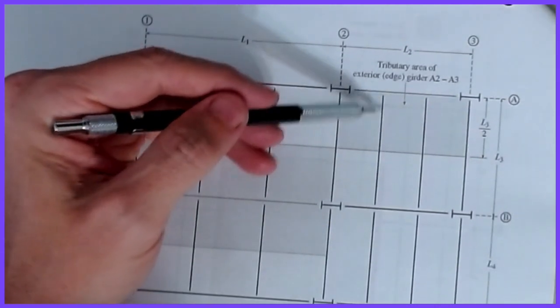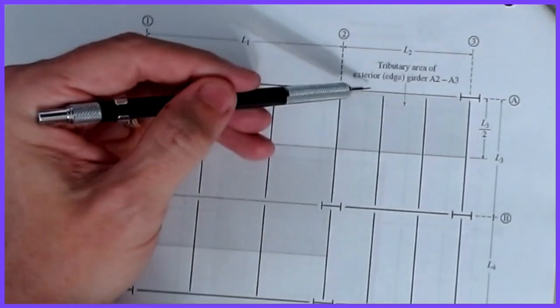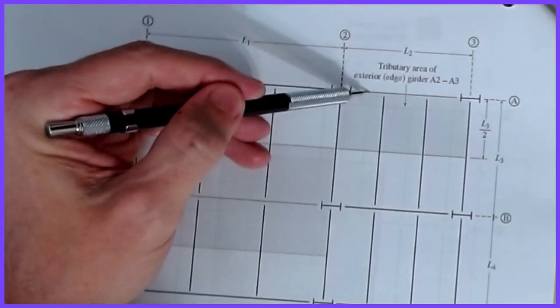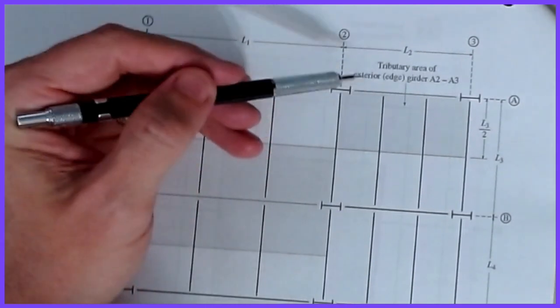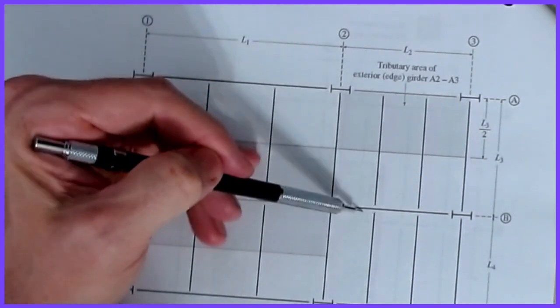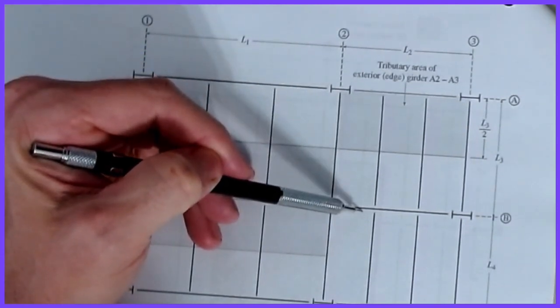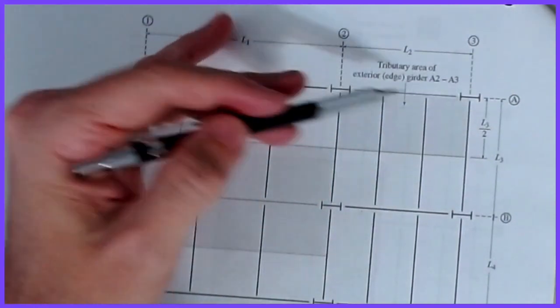So just like the beams, where I had my beam and I took half to his neighbor and half to his neighbor this way, the girders work the same way. If I just want to get a sense of the magnitude of the load, it's not exact, but it is an approximate method: I can take half of the distance between this girder and his immediate neighbor, which is this guy down here. So the distance that he's responsible for is L3 over 2,